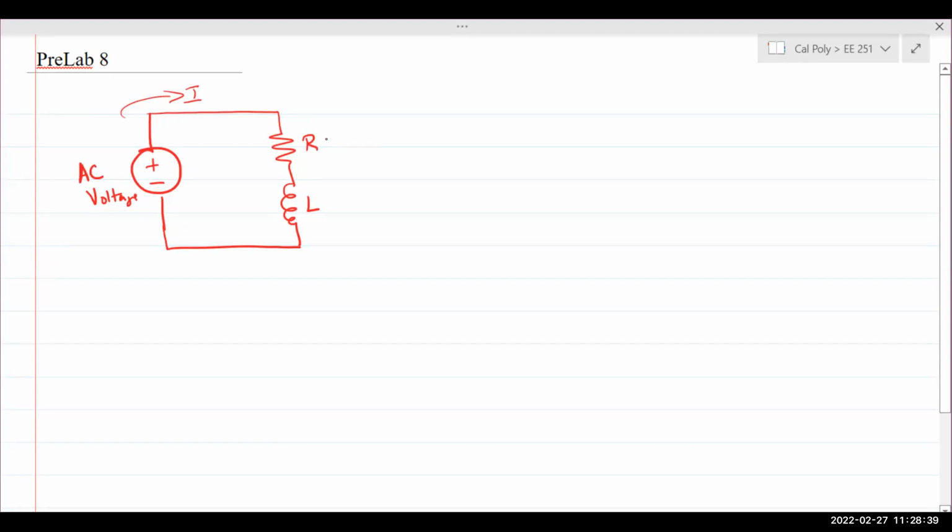Now what happens? A resistor receives AC voltage and current and behaves exactly the same way as it does for DC. So it dissipates power in the form of heat. So the power associated with the resistor is noted by P, and the unit is watts. The power associated with the inductor, however, is noted with the letter Q. The reason is it has to do with the reactance of the inductor.